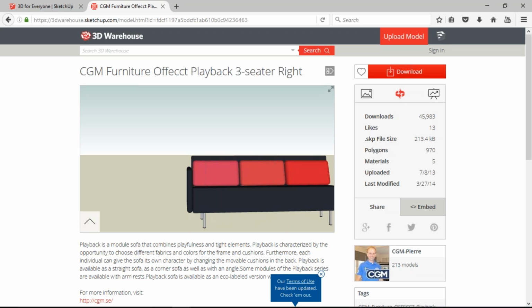So just beware when you look at the SKP file size, for example. Usually we recommend trying to be under 1 megabyte for a file size. That's going to keep your model to a nice low file size and make navigation in 3D a lot easier and a lot smoother in Envisioneer.